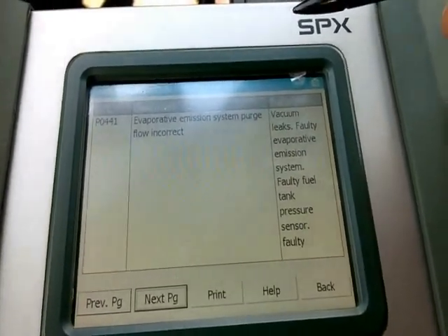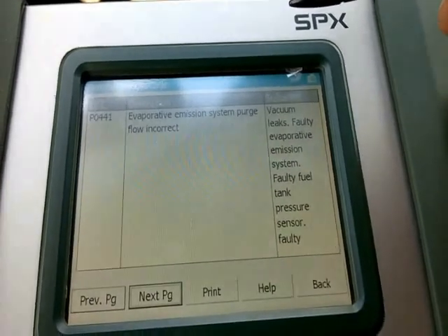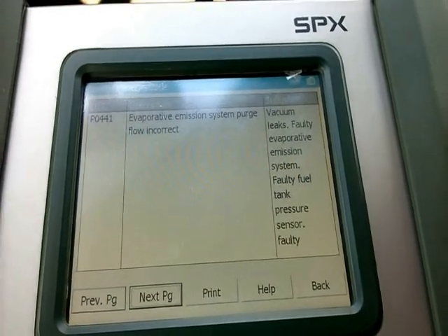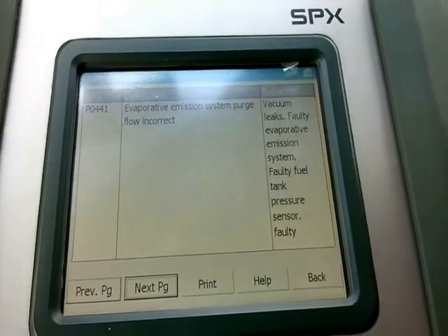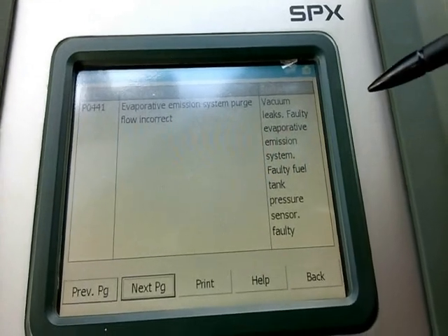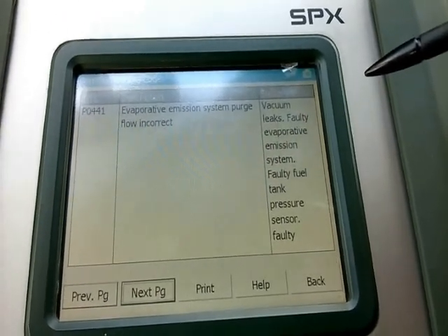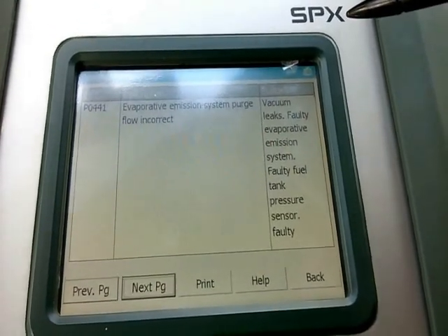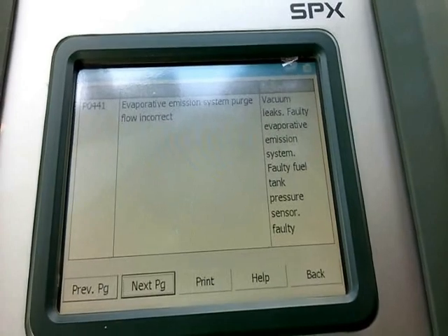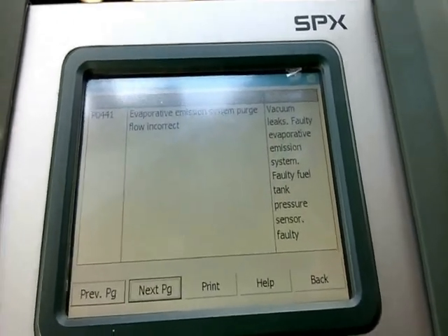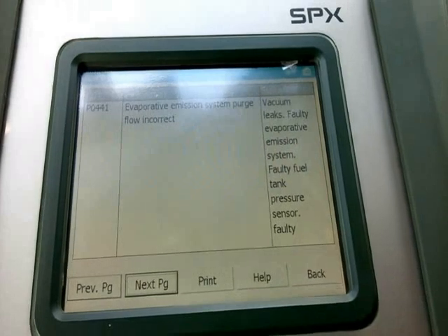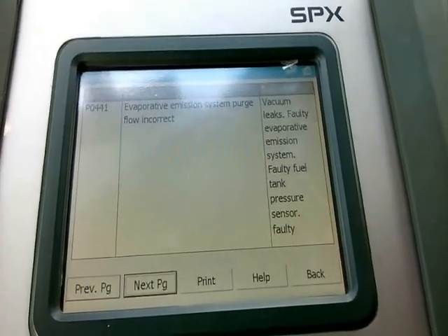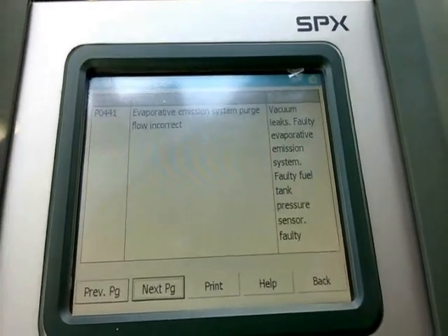So as you can see, the P0456 that we had in part 1 of this evap diagnosis is fixed. It was fixed by replacing the evap purge solenoid, which was leaking vacuum. But as you can remember, in part 1 I also mentioned that I was going to warn the customer that this P0440 may come back. It came back after, like I said, 2.5 weeks of driving, with the new code P0441 alongside the P0440.